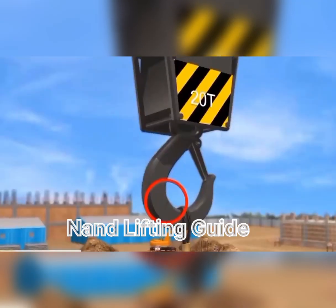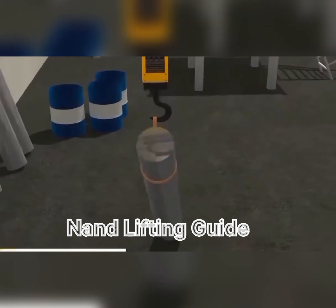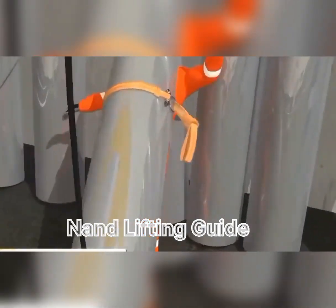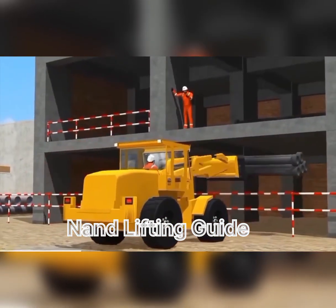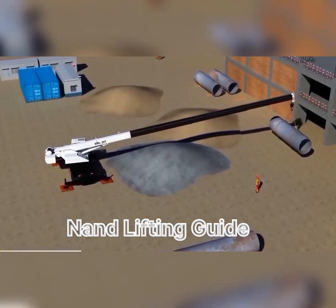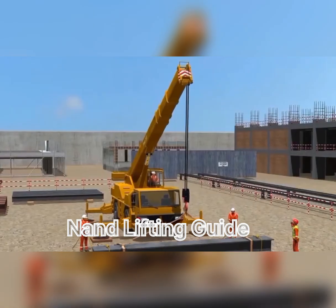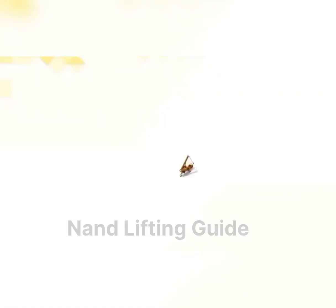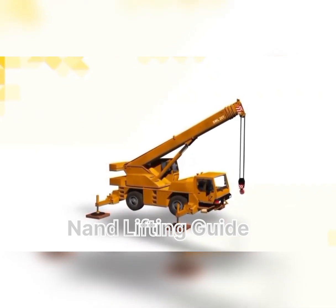using defective tools and tackles, person getting struck by and caught between load and stationary object, wrong selection of the lifting equipment, using equipment for lifting load beyond its load capacity, ignoring the safety instruction provided by the manufacturer for using a machine, not following the guidelines of maintaining the equipment according to the manufacturer's instructions.